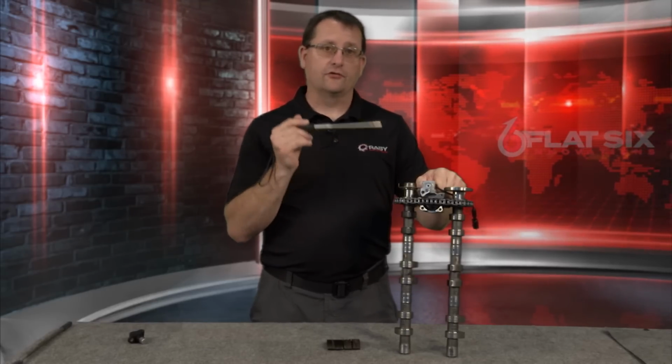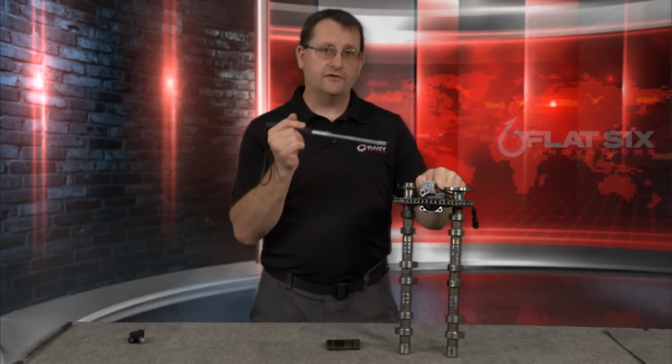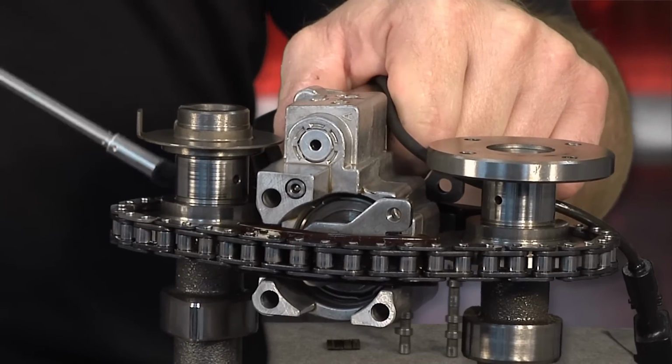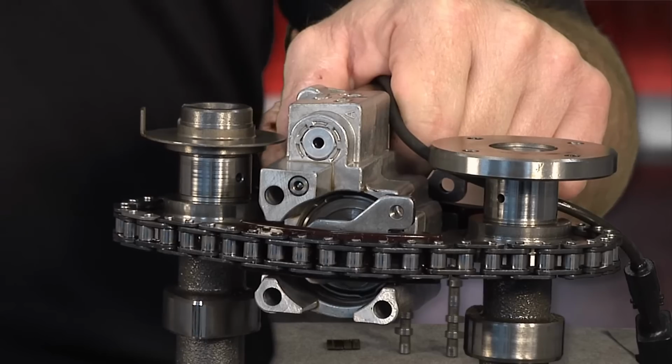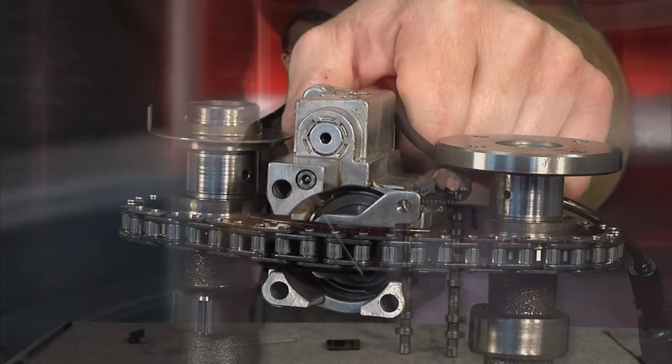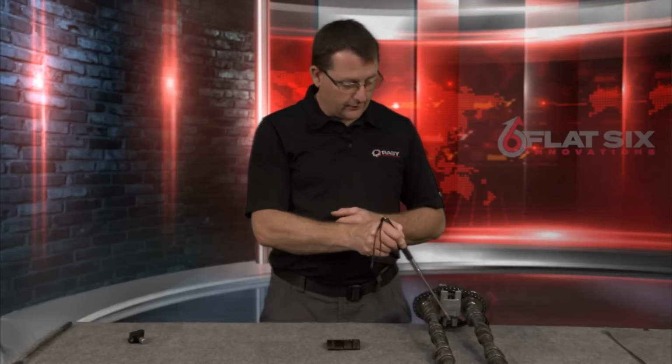So this is certainly a very repairable scenario. This is not hard to replace these components, and it's not hard to get the camshaft deviations back where they belong. We've been doing this repair for many years. Now let's go over that. So we've discussed all the things leading up to this, and really the task at hand is going to be replacing the chain guides that you see here and here on this camshaft adjuster unit.